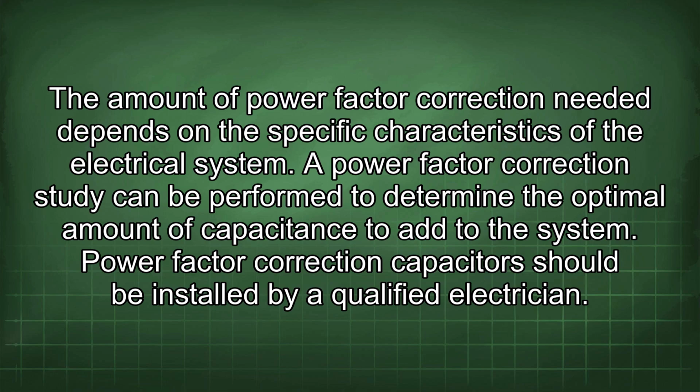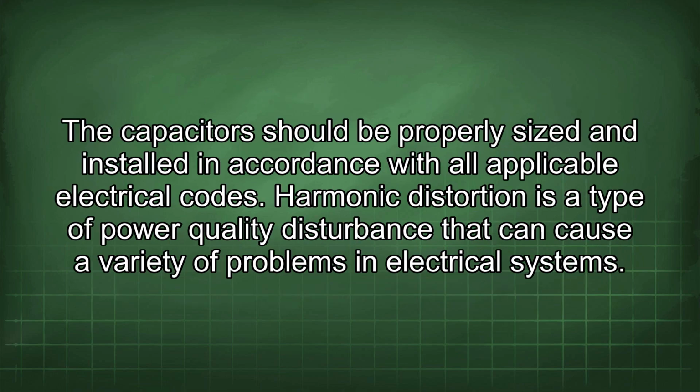A power factor correction study can be performed to determine the optimal amount of capacitance to add to the system. Power factor correction capacitors should be installed by a qualified electrician. The capacitors should be properly sized and installed in accordance with all applicable electrical codes.